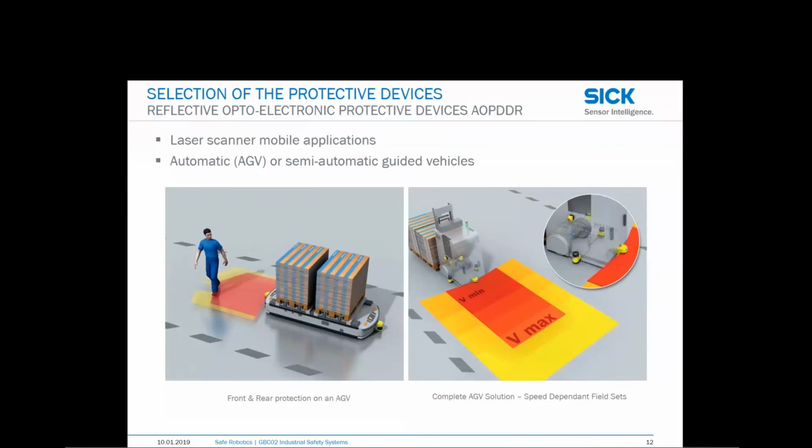And typically, 2D LiDAR is a very typical approach to doing this object detection. You can also use bumpers, but there are requirements for using the bumpers, and the vehicle still needs to stop in a predetermined way before it comes in contact with the object, even using bumpers.